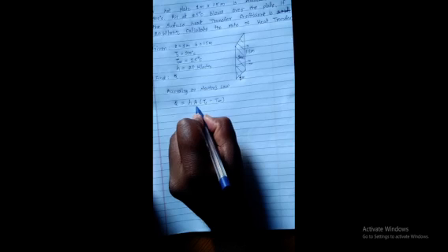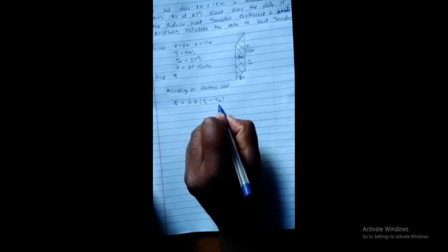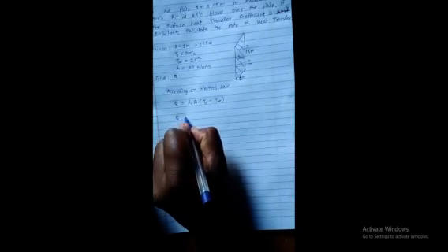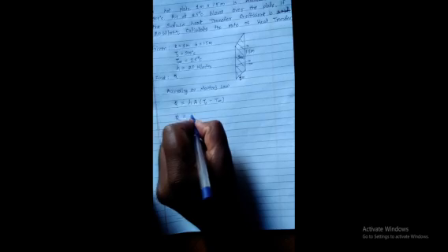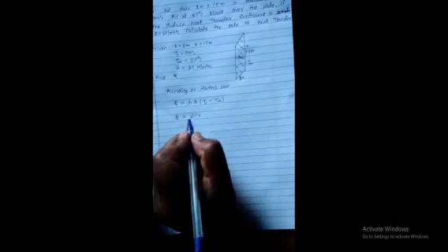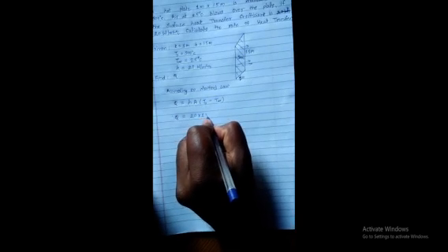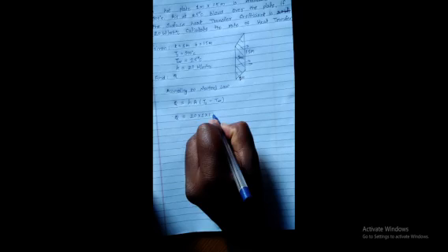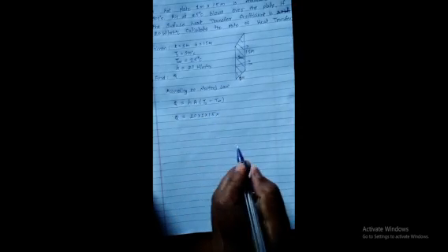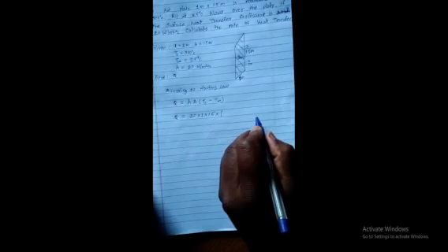So, simply we know h, we know A, we know Ts, we know T infinity, we will get Q. So, Q will be equal to h, h is 20, into A. Area of this plate is length into breadth, 1 into 1.5, into Ts minus T infinity.